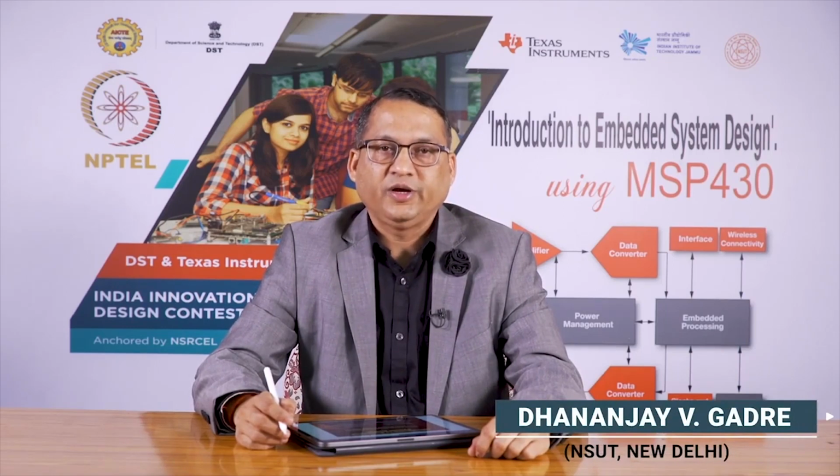In this session we are going to talk about one of the peripheral functions of a microcontroller, namely communicating with the outside world. Now if a microcontroller wants to communicate with the outside world, there are many ways of communication, but the common methods require you to send and receive data in a serial fashion. Why? Because it minimizes the number of connections that you would require for communication.